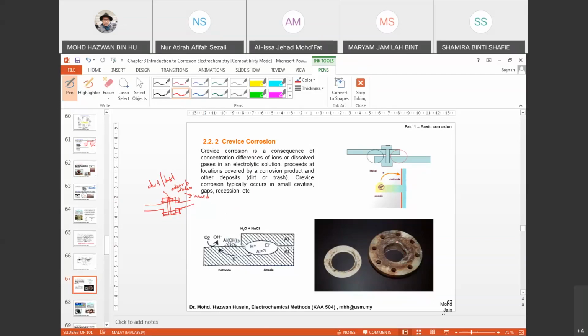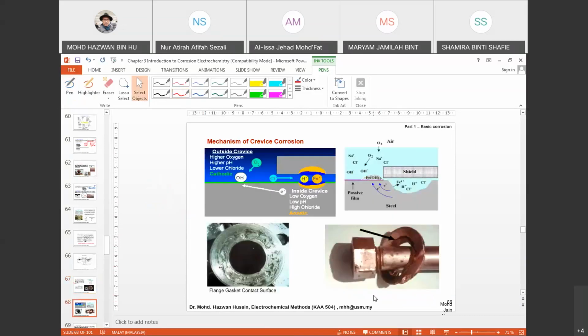That is why you see the gasket here. This is the plate lining put in between joints. You can see that probably because it is not put with a rubber ring, O-rings or others, it can trap deposits which later on can trigger corrosion. Any questions so far?